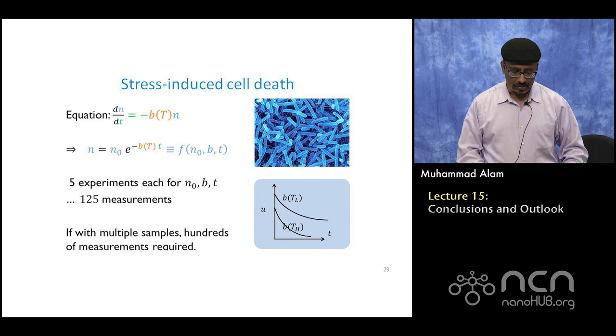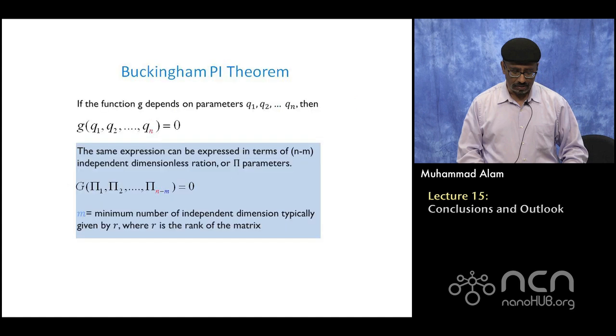The right way of doing it is not that. The right way is that as soon as you have an equation like that, you express it in a dimensionless form. If you can express it in a dimensionless form, then it will dramatically reduce the number of experiments you do with no loss of information. This is how all planes are designed and wind tunnels are done; everything is a scaled version of the big thing, and you always get things more or less right, because this is a very powerful approach, this approach of non-dimensionalization.